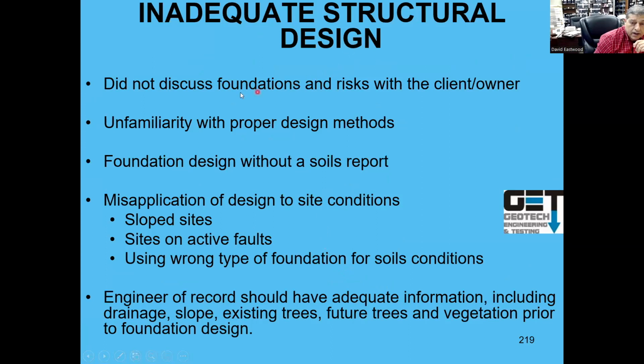Inadequate structural design. Did not discuss foundations and risk with the client. If you're doing the building, you need to talk to your client about foundations and risks. If you want a cheap foundation, you're going to have higher risk of movement. If you want more expensive foundations, you have less risk of movement. Unfamiliarity with the proper design methods. If you're doing buildings, you've got to make sure you have a structural engineer and a soils engineer that do buildings. Typically, if you do petrochemical design, you're not very good with buildings, especially residential.